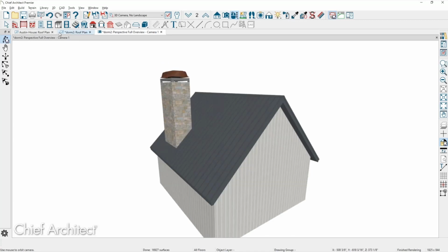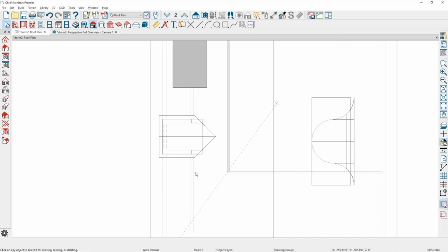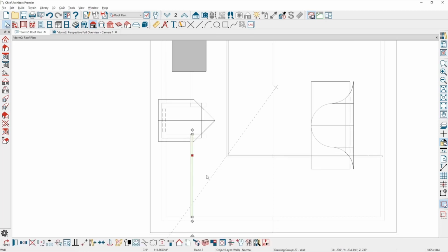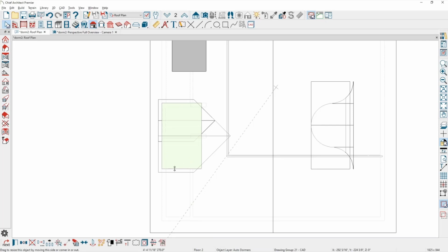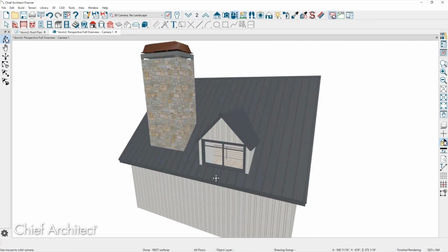Yeah. Okay. And so if I go back over into the floor plan, the program has, and it sounds like you're already familiar, the difference between a floating dormer, which is false, and a structural dormer, right, that requires walls. And when you use the structural dormer, it's looking for a knee wall, and that's basically what I have back in here, right? So if I make this a little bit larger, and then we go back into the 3D view, you want to peel this roof back, right?